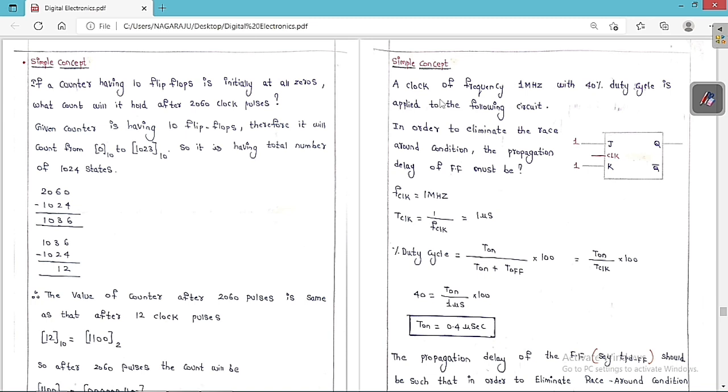So now we are going to study one more important simple concept. Listen carefully. A clock of frequency 1 megahertz with a 40% duty cycle is applied to the following circuit. In order to eliminate the race around condition, the propagation delay of the flip-flop must be...